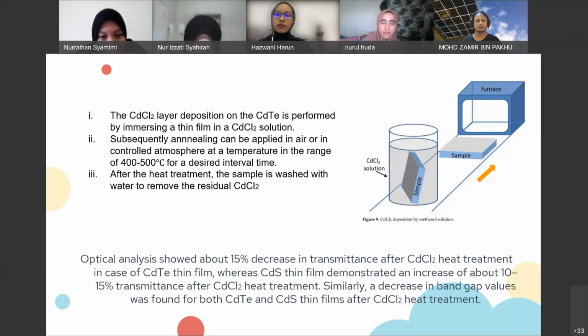Less, right? But the border between the grains will be smaller, right? If you have the same thickness, 2 to 5 micron, let's say 2 micron, with small grains, you're going to have more grains and therefore more boundaries. The more borders, it's like a maze: you have to go through many wires, and can't get out. The carriers get stuck.